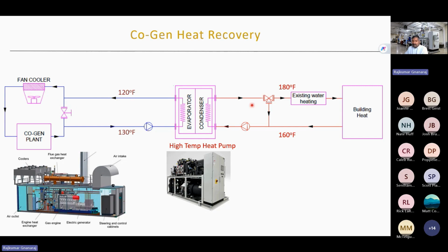And on the condenser side, we can achieve hot water at 180 degrees Fahrenheit, and you can use it for any kind of heating application in the facility. So this is another application where you can integrate the heat pump using the waste heat from a packaged CHP unit.